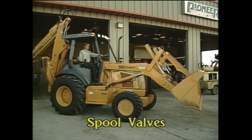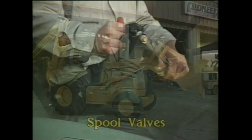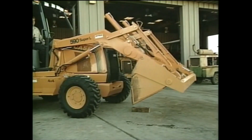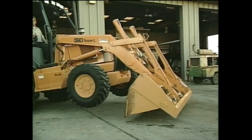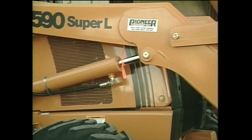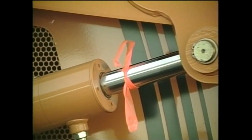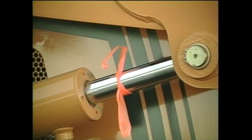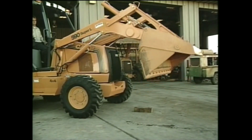Let's see how to check the spool in a directional control valve for internal leakage. Directional control valves can be field tested for internal leakage by pressure loading an actuator like a cylinder, then shutting off the engine and watching for the cylinder to settle. If there are no external leaks, any settling that occurs is caused by internal leakage in the directional control valve circuits. We will see why this is true in Part 7, where we cover cylinders.